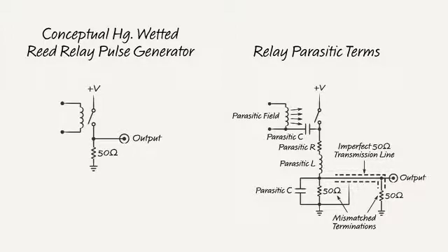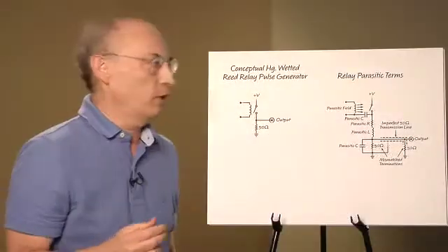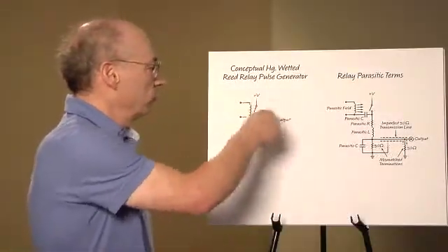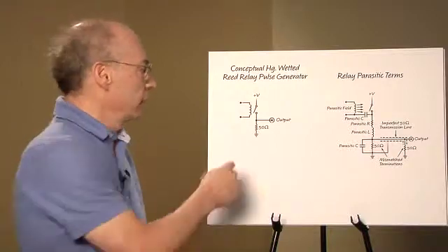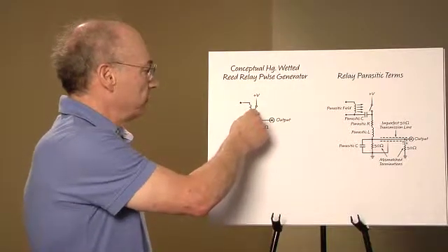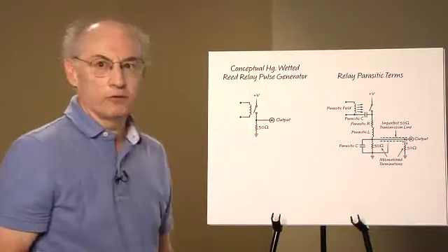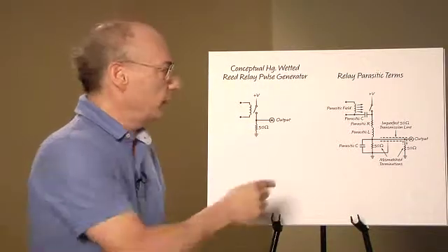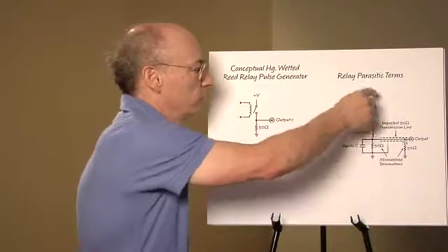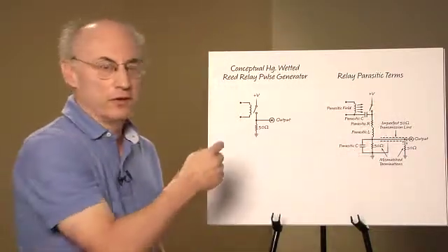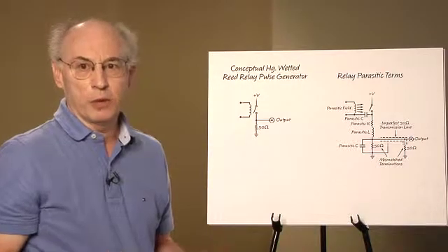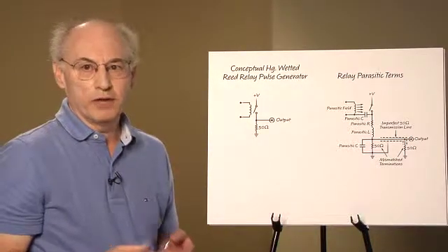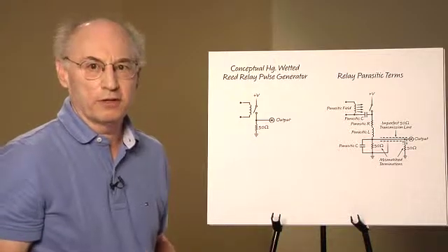A good question at this point might be, how do you know the settling time fixture is trustworthy? How do you test it with something that approximates an ideal input, an ideal DAC? And the surprising answer is, you test it with a reed relay. In theory, when these switch contacts open, the voltage settles across this 50 ohm resistor instantaneously. In practice, there are lots of parasitic resistances, capacitances, and inductances in the signal path. They're going to get in your way, and most practical reed relays take on the order of 1 to 2 microseconds to settle to a part per million.